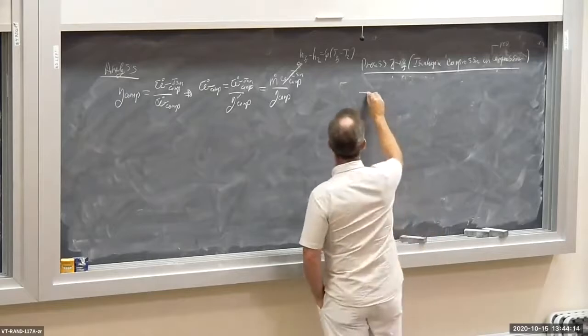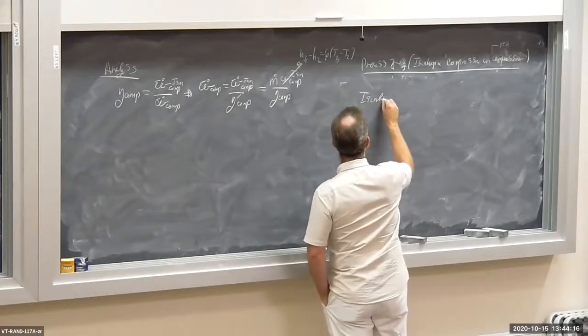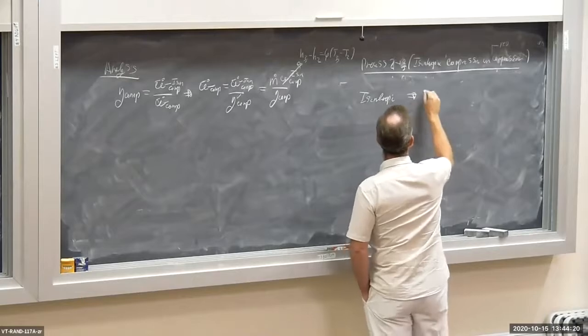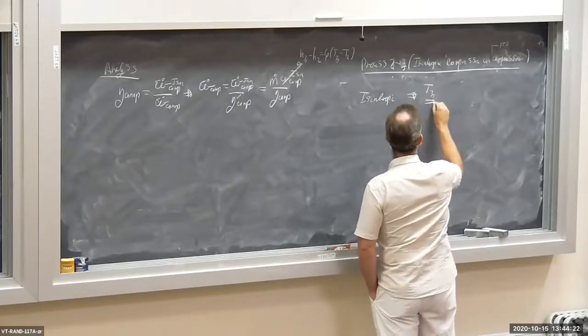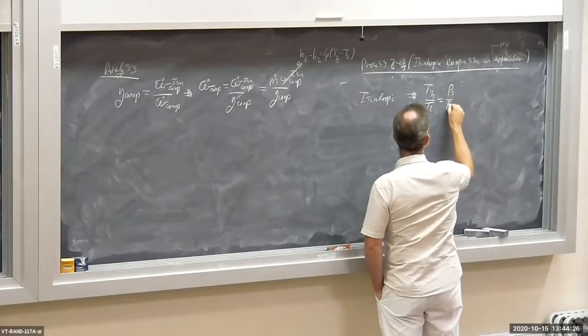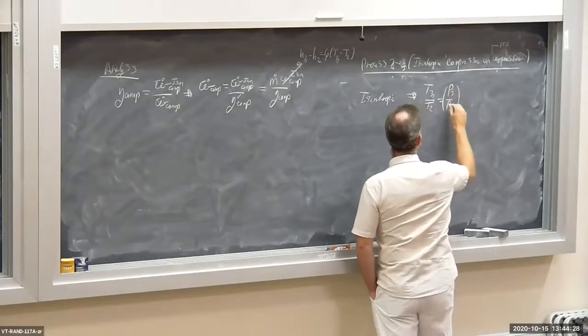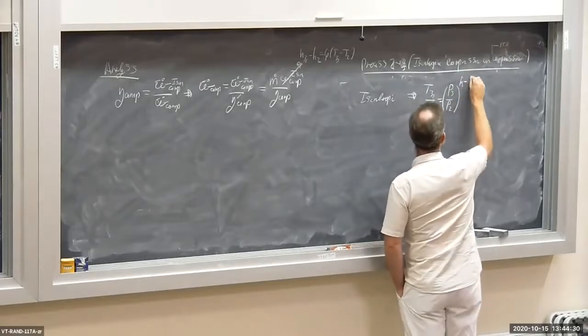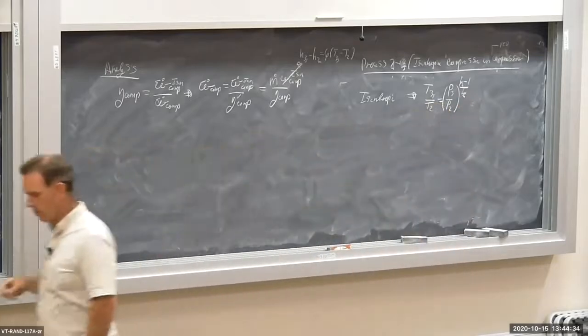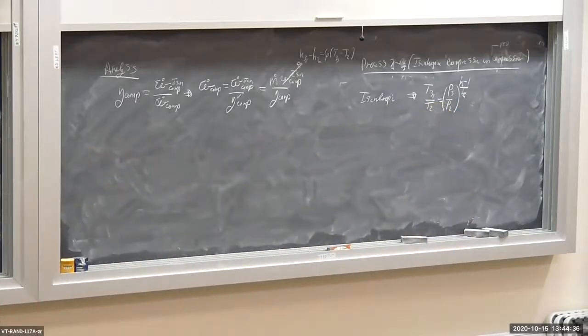So it's isentropic. So that means the following. T3s over T2 is equal to P3 over P2 to the (k minus 1) over k power. Oops, make sure I got that right. Sometimes I get the exponents wrong. Let's see here. Yes, (k minus 1) over k.